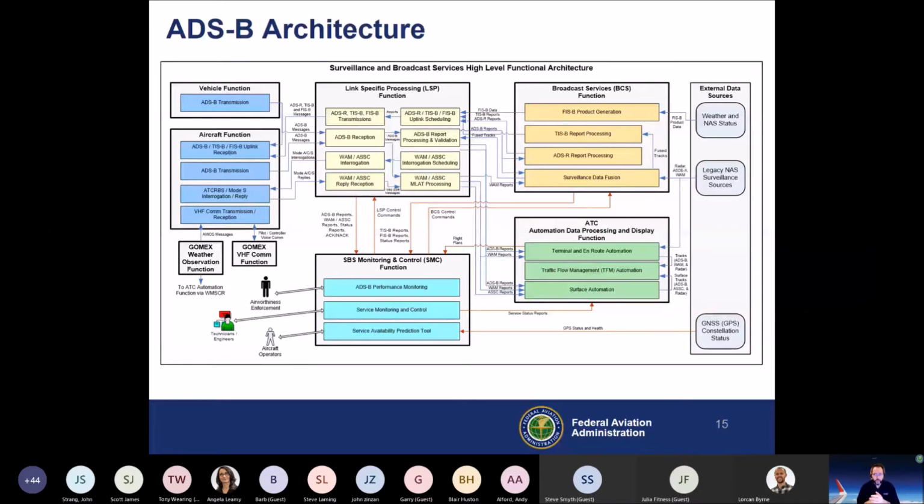There are also times when ADS-B broadcasts the position incorrectly for whatever reason. You have malfunctioning avionics, and it has happened in the past where that information is fed to air traffic control. We now have a very sophisticated validation process which will throw that information out if it's deemed to be inaccurate.